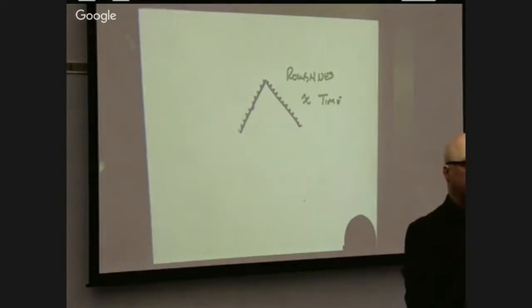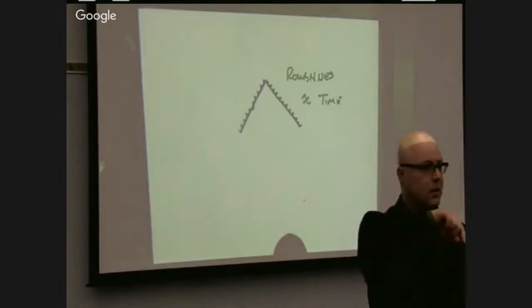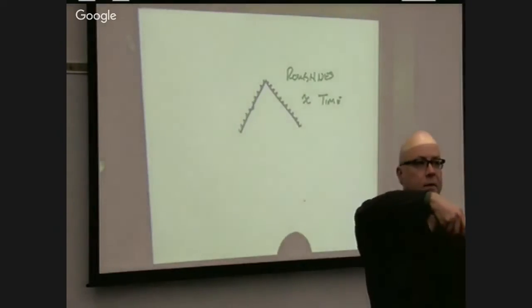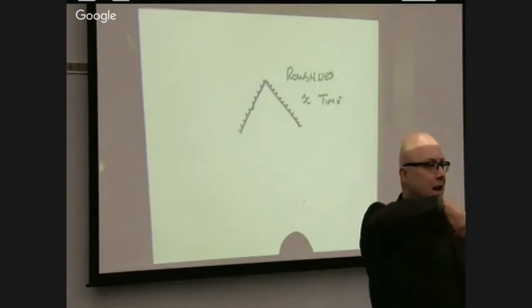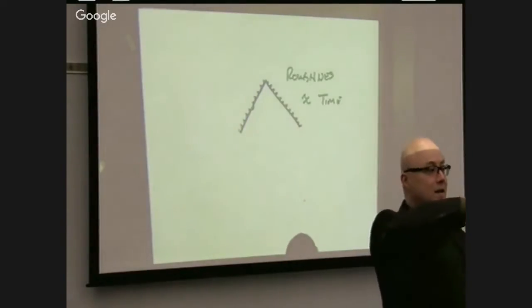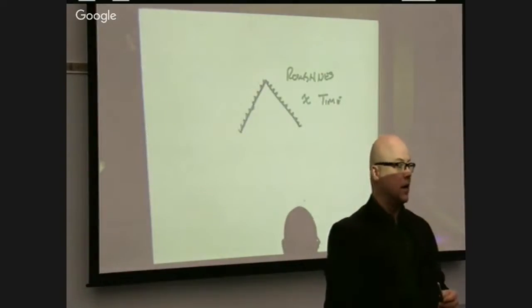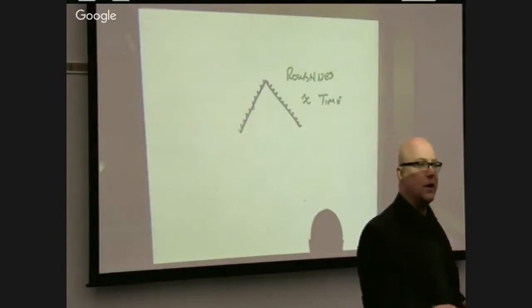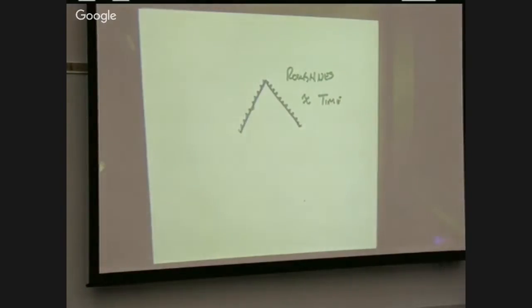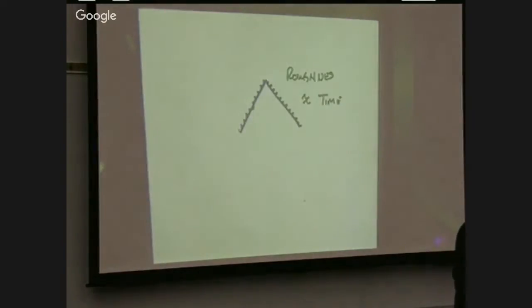If you get those tuned just right, the deflection changes orientation depending on the rotation of the tool. So if you get those timed just right, you can set up a resonance, and you get that thing humming. It sings, it makes noise, and then you'll get what's called chatter on the surface. My guess originally, because I didn't think about the tolerance, was that it was the length of either the workpiece or the tool that set up some resonance that was getting chatter. So that could be it.